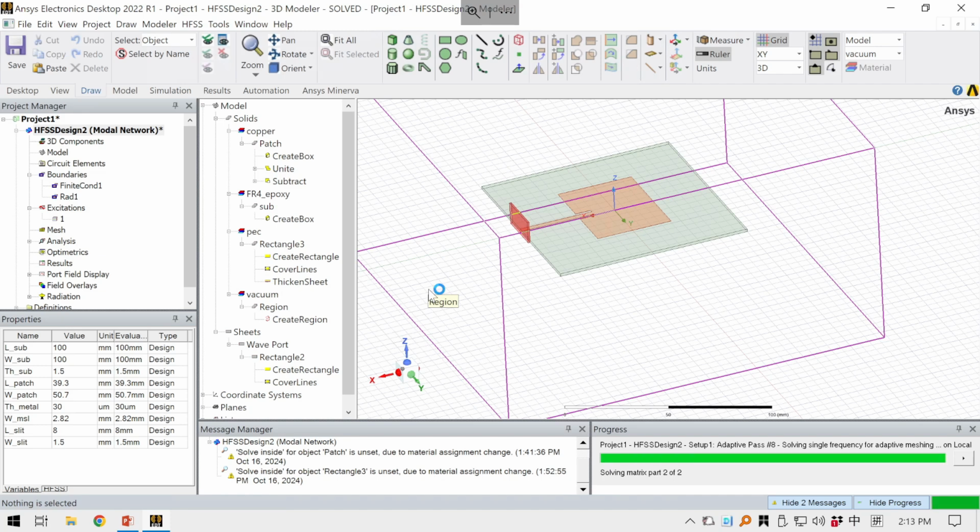The working principle of waveport is that it will extend to infinity using the same cutoff plane. So, for example, next time you design a, let's say, 70 ohm transmission line, it will automatically create an infinitely long 70 ohm transmission line behind it, but you cannot see it.